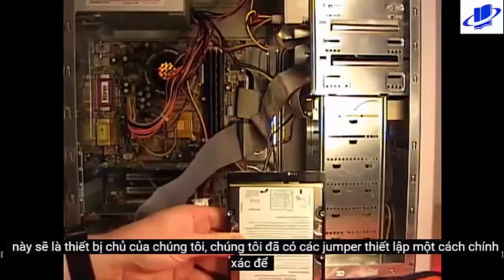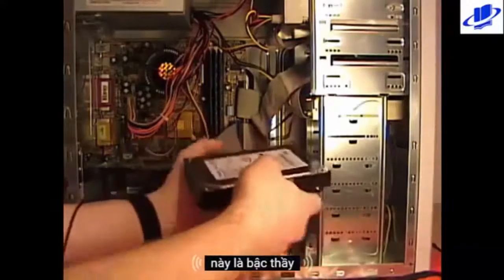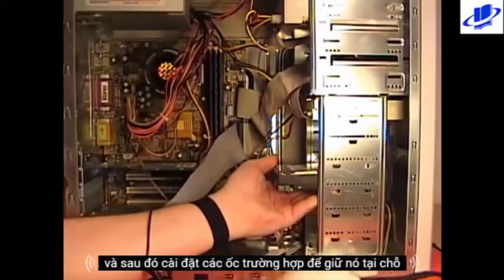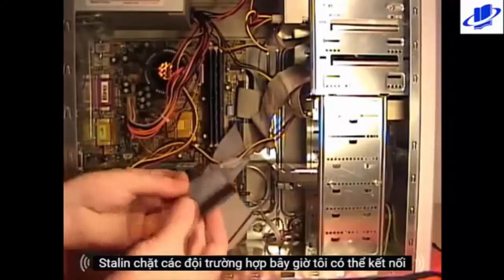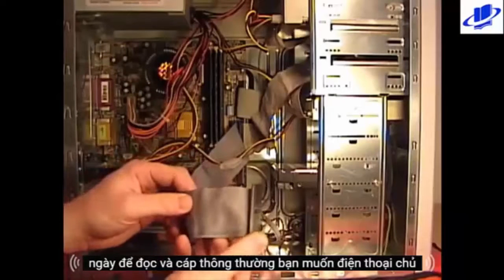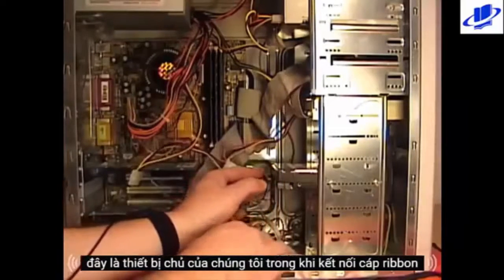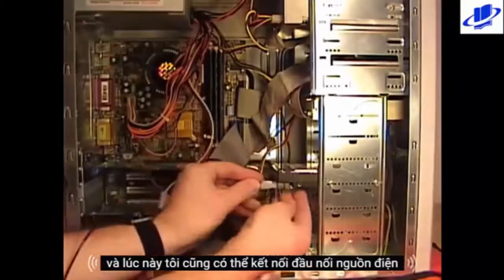This is going to be our master device. We've got the jumper set correctly, so this is the master. Carefully insert this into the computer case and then install the case screws to hold it in place. Installed and fastened the case screws. Now I can connect the data ribbon cable. Generally you want the master device hooked to the end connector on the ribbon cable. This is our master device, so I'll connect the ribbon cable, and at this time I can also connect the power connector.